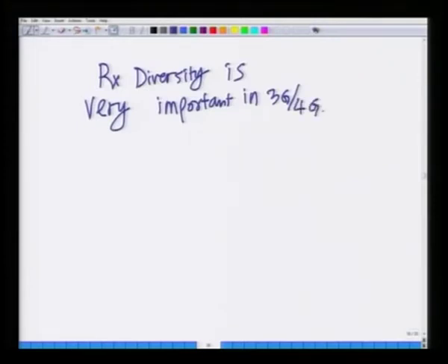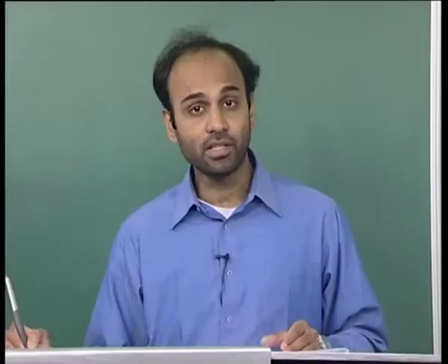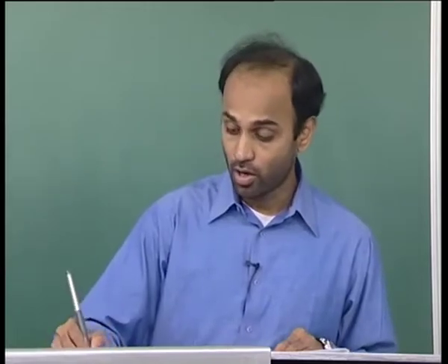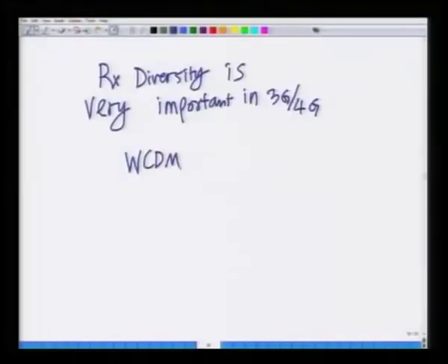Receive antenna diversity is a key aspect in 3G, 4G wireless communication systems. It is employed in WCDMA, it is employed in HSDPA, it is employed in LTE.